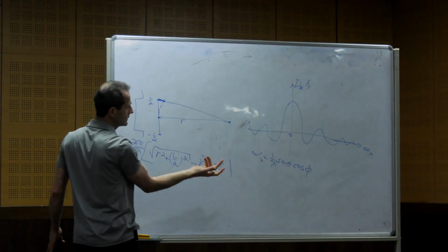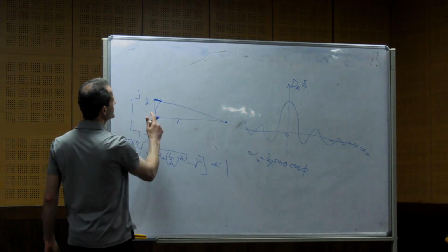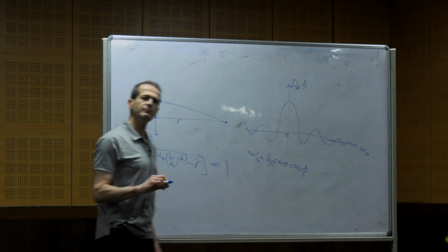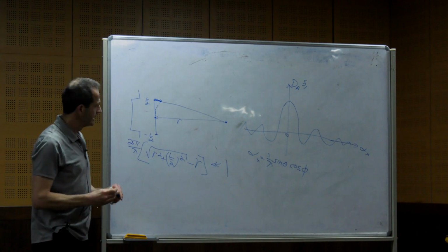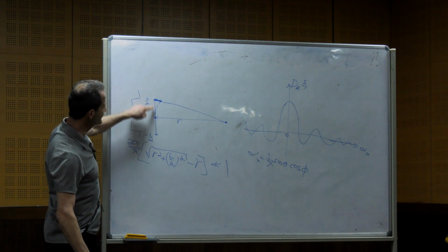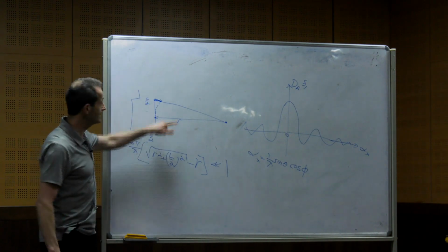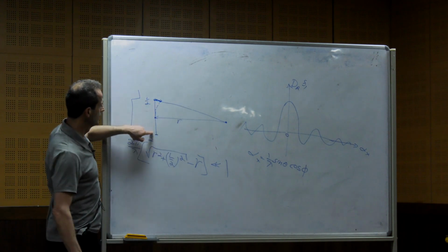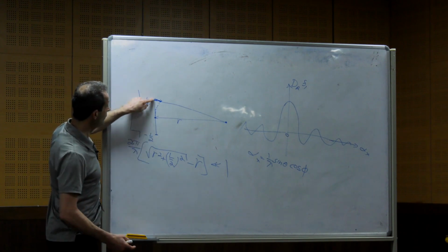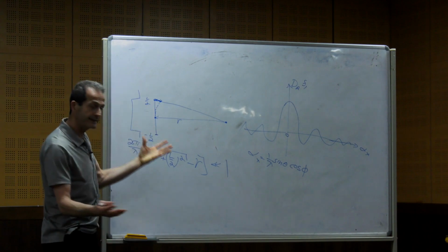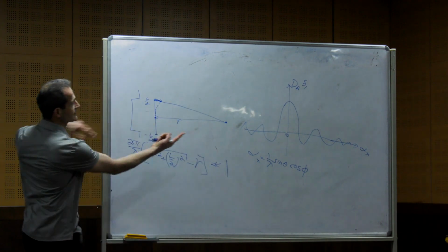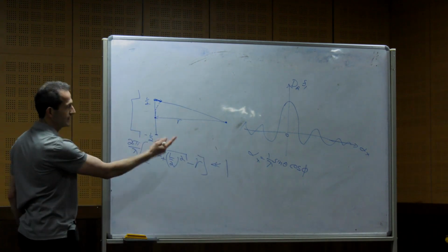Theta equals 0. So all these directions, it will be maximum. And think about why. What is the reason? If it comes from this direction, and you have the line, and the response is the same, it doesn't change the phase that hits each point. So you have constructive interference. It combines all the signals that hit every point here, and it accumulates into the strongest signal. And then, of course, it has symmetry, like circular symmetry. That's why you have it here.